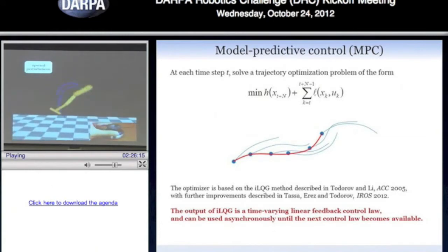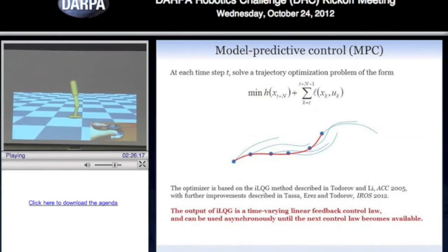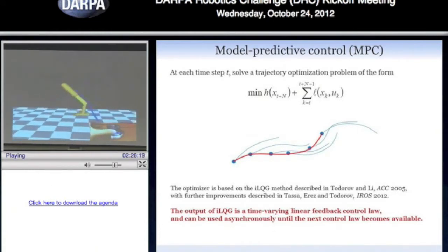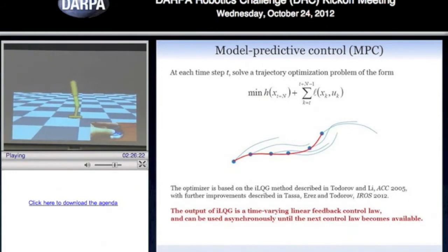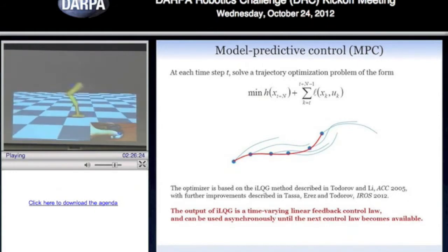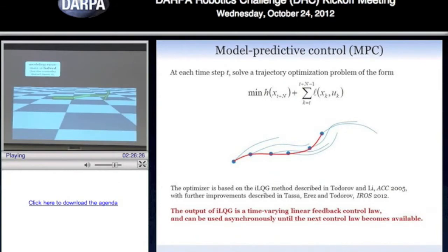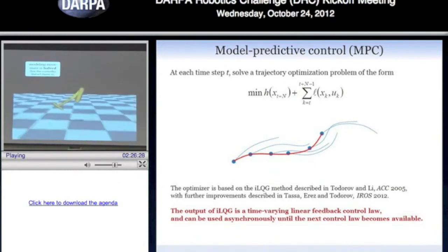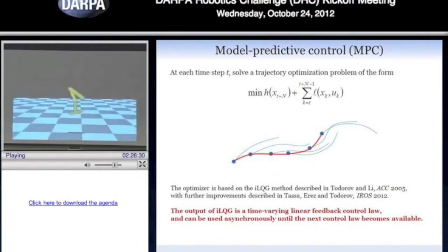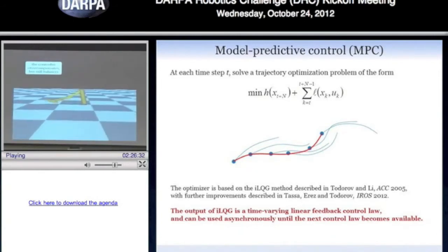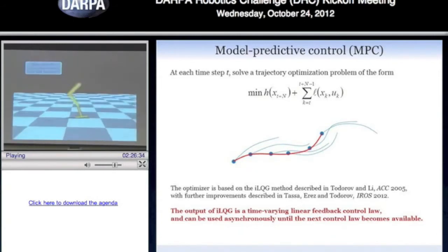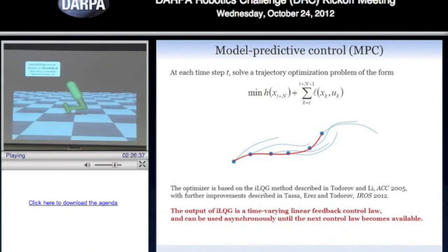It doesn't have any control strategy that's being pre-computed, let alone hacked. This emerges completely in real time. It can invent all kinds of things like somersaults and stabilizing strategies. This is really important. So we're going to introduce a huge model error here. We make the mass 2 times smaller. The controller has no idea we changed the mass. So it's working with a wrong model, and yet it kind of works.